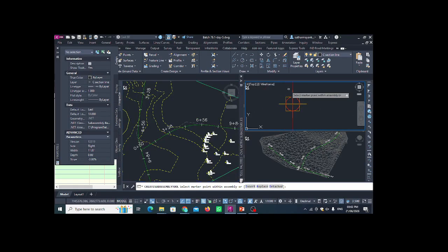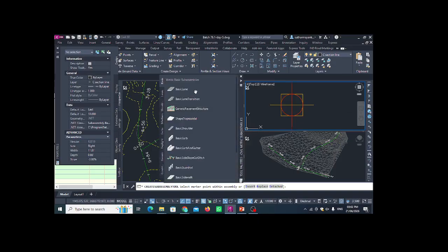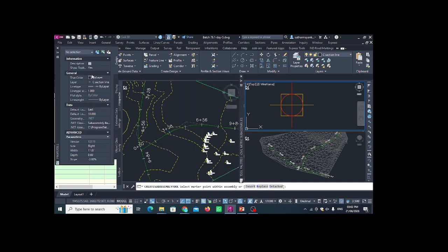Here you can see this crown part. So if I want to put that road, I have to put it here. Before that, as we click here on the basic lane, we have these properties for that basic lane. Now ignore this above part, come here into the advanced part. You can see the side is right, and the width of the road is this. Here you can see all the things in feet.